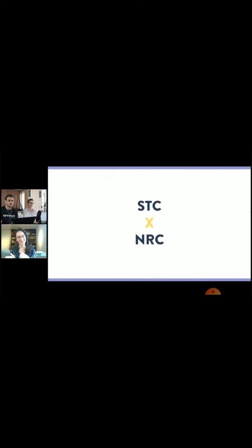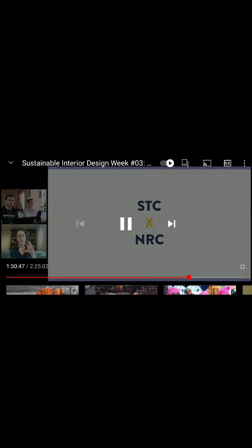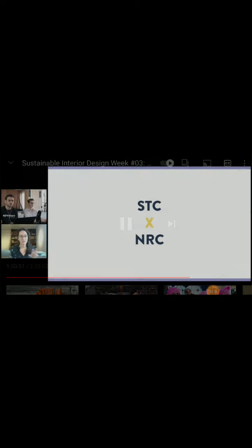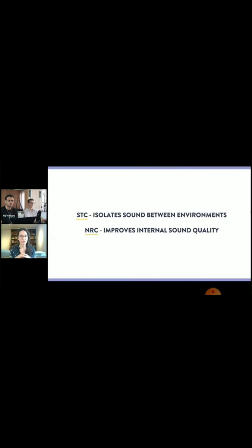And this takes us to the absorbent materials, which are the porous material that the sound goes in and loses intensity. And the last one, that is the one that does this diffraction of sound that diffuses the sound everywhere. And therefore, it also loses the intensity. So we first talked about STC, sound transmission class, the sound that is outside, the noise that goes inside. And now we are talking about NRC, noise reduction coefficient, okay? This noise reduction coefficient is the metric for the indoor sound. That's what I want to do inside, okay?